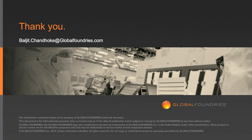One of our viewers has a question about the higher frequency applications. Can you use RF SOI for 60 gigahertz and above? Absolutely. Like I was mentioning in the presentation, you want your FT/Fmax to be at least 3 to 5 times your application frequency. In this example, 60 gigahertz is a very commonly used WiGig frequency as well, and we have customers designing for WiGig today with 45 RF SOI.